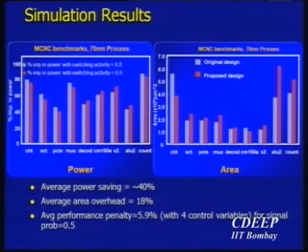So if you look at one process corner versus another process corner, and you really want the highest yield, you need to look at each of those process corners. And there's a wide variation in leakage, right? So if you don't do some sort of self-timed approach, leakage is going to be the dominant power consumption. So from a power consumption point of view, it might make sense. The only problem, and that's always the problem with any asynchronous methodology, is that if you want to go fully asynchronous, I need to know completion, right?